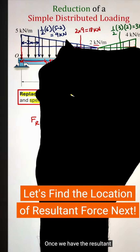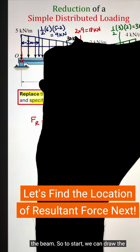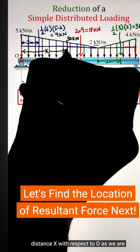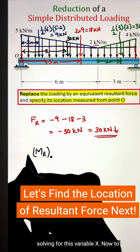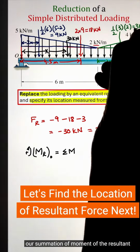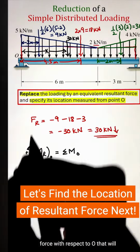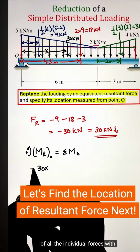Once we have the resultant force, let's identify the position on the beam. So to start, we can draw the resultant force on the beam and specify a distance x with respect to point O, as we are solving for this variable x. Now to calculate the value of x, we can utilize our summation of moment of the resultant force with respect to point O, that will equal the sum of moment of all the individual forces with respect to point O.